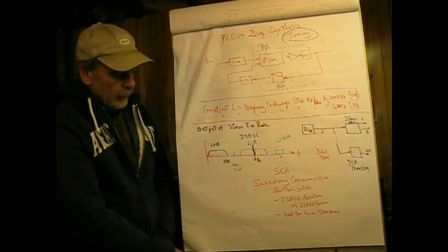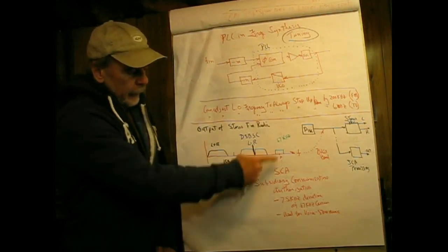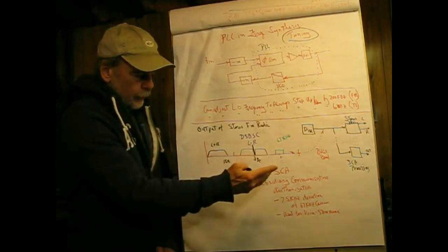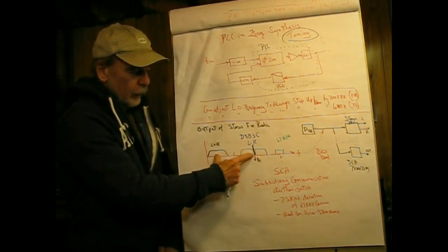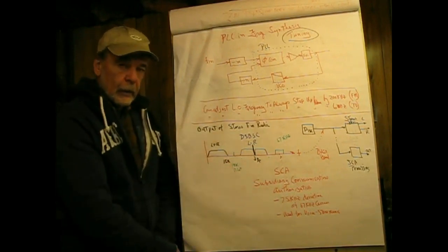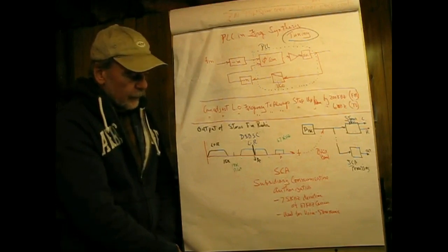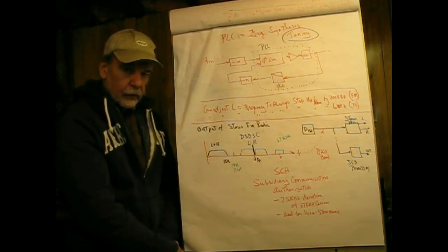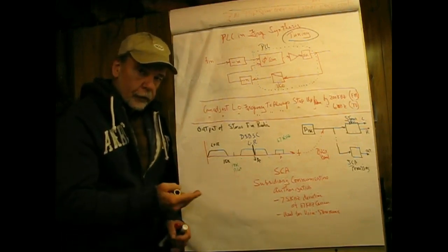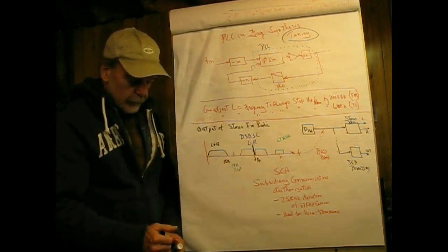Now, how much stuff can we stick on here? Well, some of the deviation that's used means that it's not available for this, and what we saw on the previous page is that the audio output is proportional to the deviation. So what that means is the audio output will be a little bit less, which means it'll be closer to the noise floor. So this is not free on board. There's a noise penalty to pay for this.